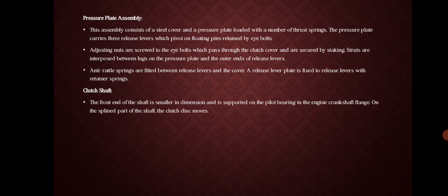Struts are interposed between lugs on the pressure plate and the other end of release levers. Anti-rattle springs are fitted between release levers and the cover. A release lever plate is fitted to release levers with retainer springs.